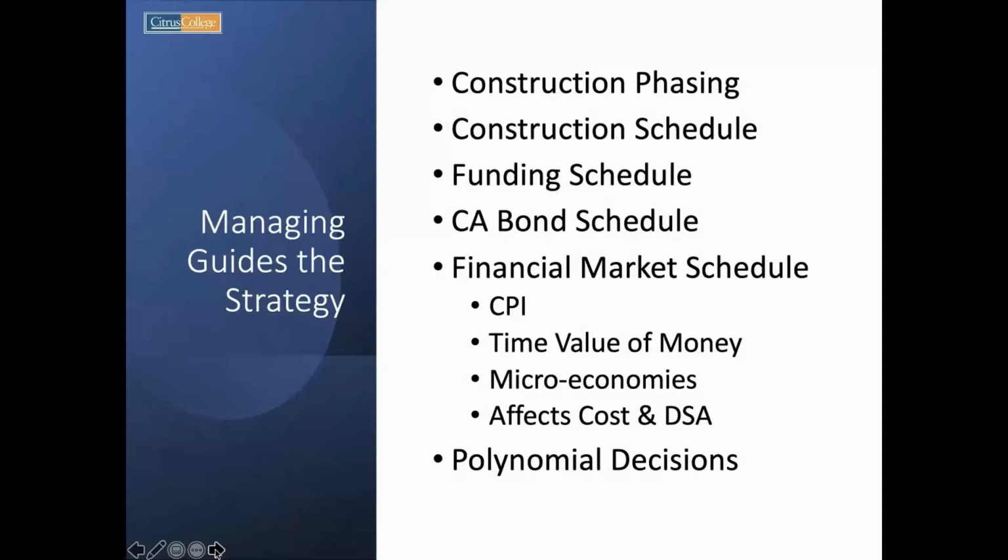We've done a number of repairs, but we do have one thing on campus that kicks in a safety item, even though I wouldn't say that it's a danger or anything like that, which it's not, but it does make it entirely viable to undertake a safety project. So a number of years ago, unbeknownst to the district, when they brought in a modular classroom building, where they happened to land it was directly over one of the trunk lines on the fuel gas side. If you look at the mechanical code today, even back then, you're not supposed to place a building over a trunk line.